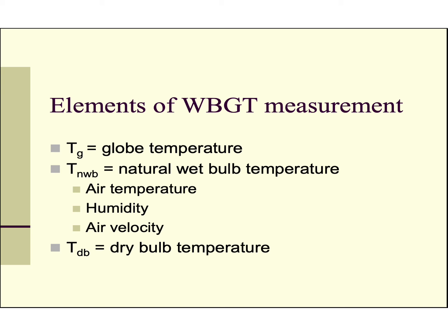You may hear about wet bulb otherwise, and that's usually referred to what's more specifically called aspirated wet bulb, where the thermometer is moved rapidly through the air, or air is mechanically blown over it to determine the relative humidity. But this one is the natural wet bulb, so there's no artificial movement of the air. Then lastly, there's the dry bulb temperature, which is just the ordinary air temperature measurement that we're normally accustomed to.